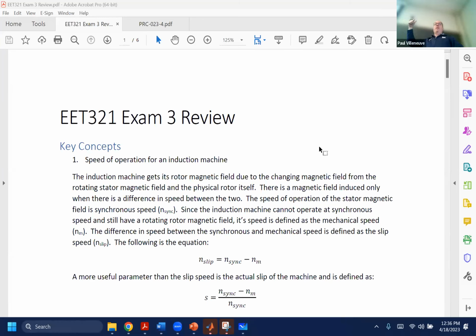So what I mean is normally we have a radial feed, which just goes out. A loop feed means it goes out, but then something else comes around and they come back to the same point. It's kind of like campus. Campus is the loop feed as well. Yeah, so it could be 2 3-phase lines, but generally speaking, if you have 2 3-phase lines, usually it's not the same voltage level. It would be a higher voltage and a lower voltage. So it could be that it was a 46 kV.